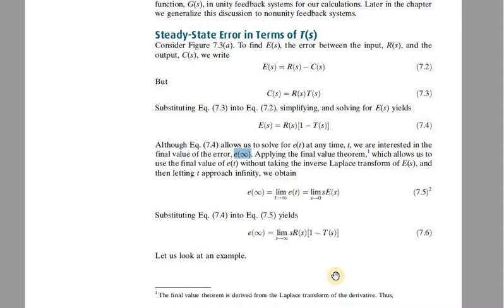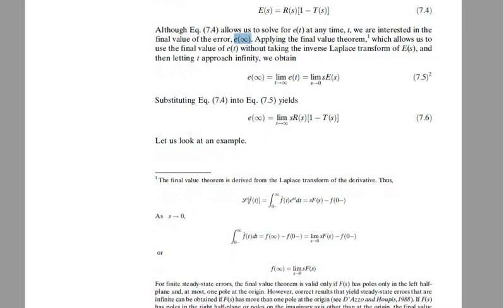You remember when we studied the final value theorem, there is a condition that it is applied only when we have a stable system, meaning the poles of the closed loop system must be in the left half of the s-plane. So this condition also applies here. This only calculates for stable error. If error is growing, this formula no longer works. So for calculating steady state error, our system must be stable, or in other words, poles must be in the left half plane.